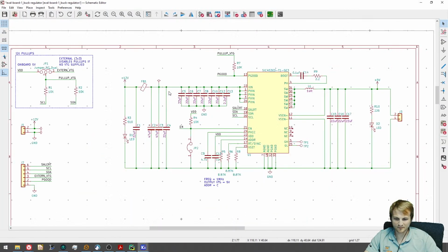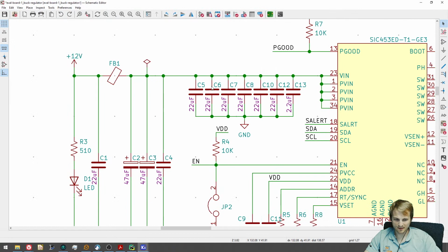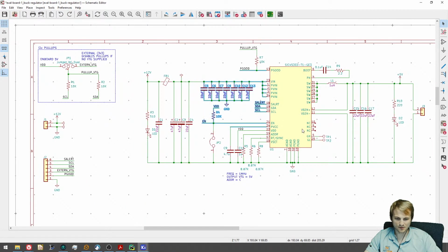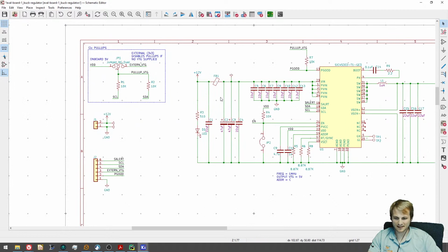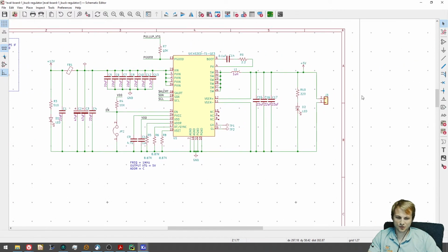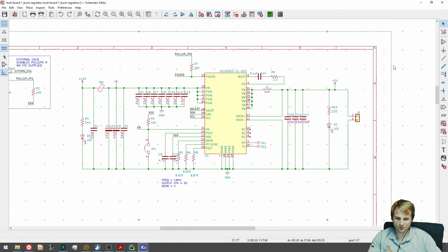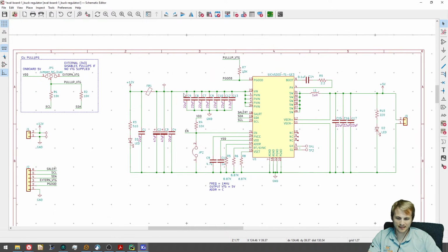Okay, so from this point on, since these are all going to be super close to the regulator, everything upstream from here and back to the wall's power supply has a decent bit of inductance. So if there's a big transient on the output side, or it just ramps up to a high current, these ceramic caps are going to get depleted fairly quickly.